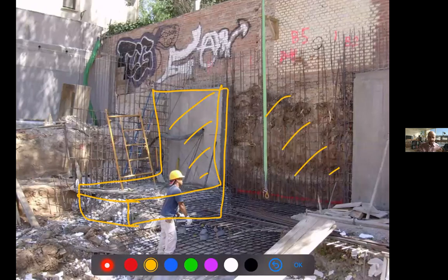And in this case, all this kind of a waterproof, this kind of layers, right? So with gravel, it's impossible because we don't have space. So on one side we can do it, and the other side it's impossible. So in this case, we will have to waterproof on the inside, or we have to resort to other strategies, right? Because we cannot work. We can put something in between, but in this case, we chose just to put the concrete against the wall and as fast as possible to avoid the danger of this falling.